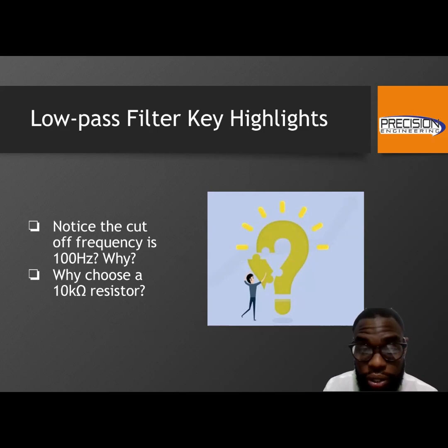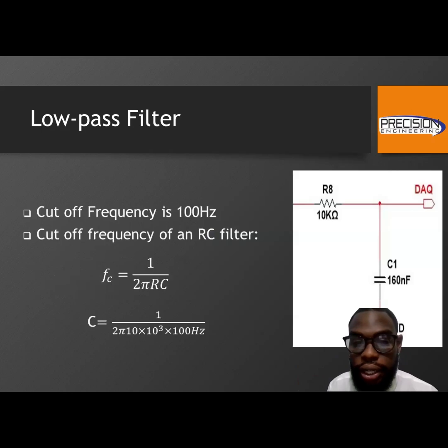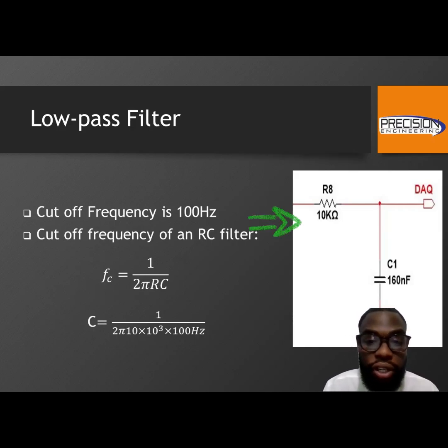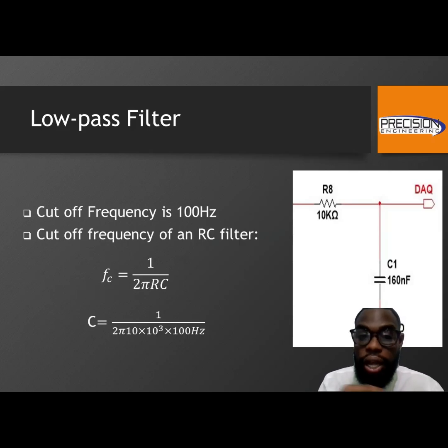Without accurate measurements, we cannot accurately build a product that will work to the characteristics of an actual top-end strain gauge. Having done that, it's also key to know that the DAQ does operate with a certain impedance. So the high output impedance from the strain gauge and the high input impedance that is now introduced from the filter help with the operational impedance necessary for the DAQ.